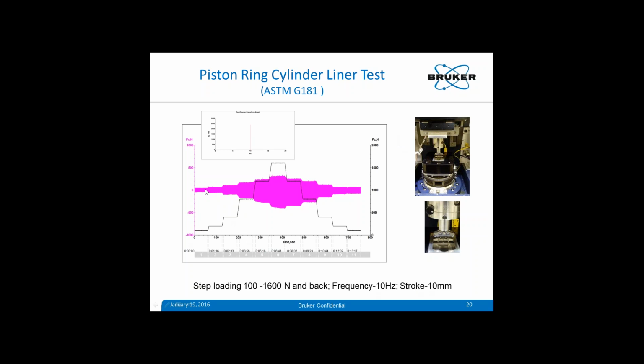FX actually shows, because this is a reciprocating test, a sawtooth or square wave kind of morphology for this particular plot. And if you do a fast Fourier transform of this data, you see there is a frequency of 10 Hertz.